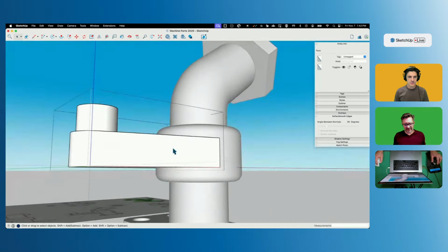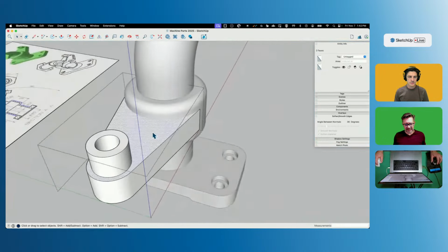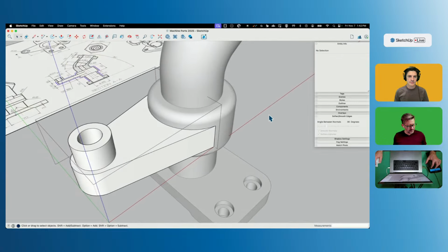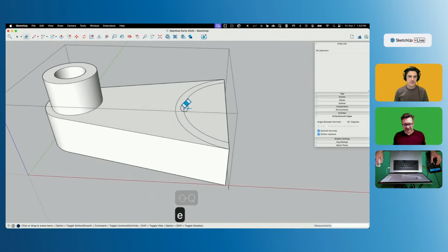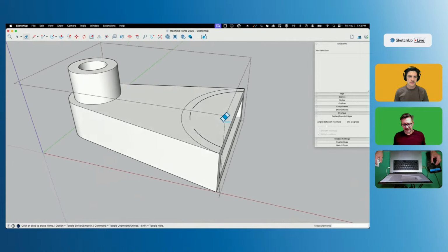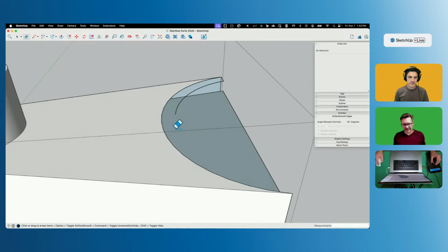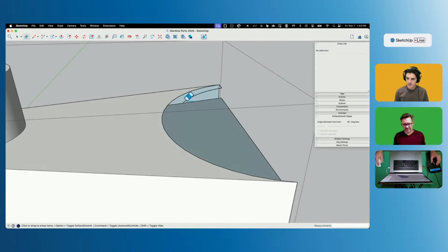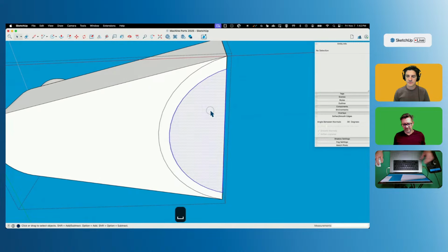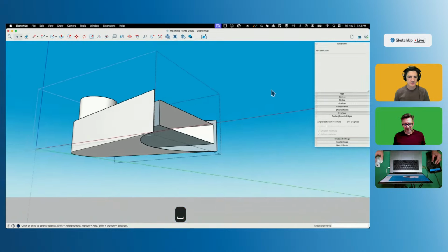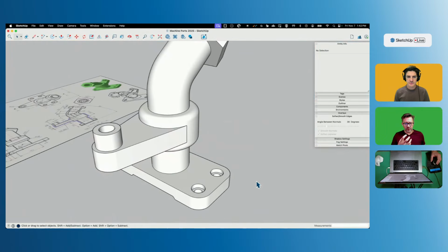So specifically, if I come and grab that face and this face, and I say intersect face with model, and then I'll hide everything again. Now I know I can get rid of, I don't actually need that. But I can get rid of that. That all goes away. And then, same thing on the bottom. I guess I just delete that. Less cleanup, just get rid of it. All right, so then that is exactly how it will meet this outside piece.